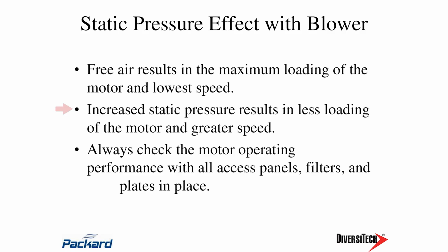If I put the door back on the furnace, does that change my static pressure? If it changes the static pressure, does it increase it or decrease it? It increases the static pressure. So if it increases the static pressure, what will that do to the load? Less load. Now wait, does this stuff make any sense? That's not what we saw with the fan blade. As I increased the static pressure with a fan blade, it increased the load on that.